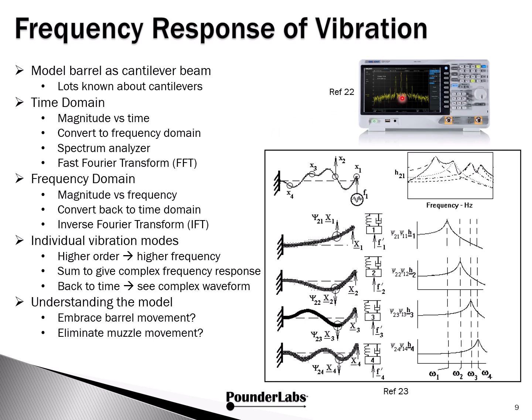We could use a signal processing system called a spectrum analyzer to see what the spectrum looks like, but numerically, we can also use what's called the fast Fourier transform. In the frequency domain, we're now looking at magnitude as a function of frequency, and we can convert back to the time domain using the inverse Fourier transform.